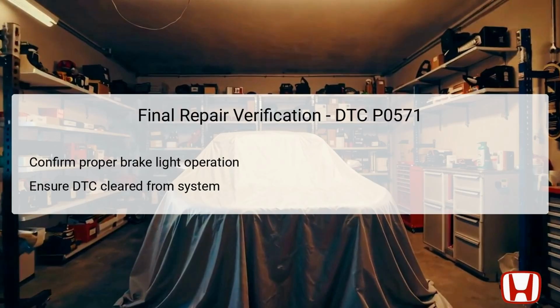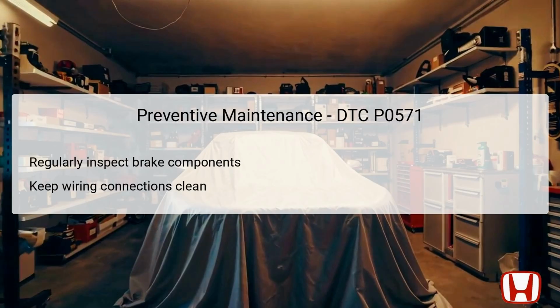This step serves not only to satisfy the necessary repairs, but also to reassure the driver of safe operation and reliability of the vehicle. To prevent issues and avoid triggering DTC P0571 in the future, regular maintenance practices should be established. Begin with consistent inspections of the brake pedal position switch and its related wiring to check for any signs of wear, damage, or corrosion.